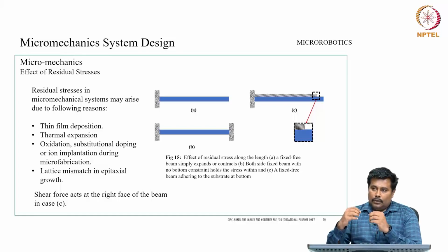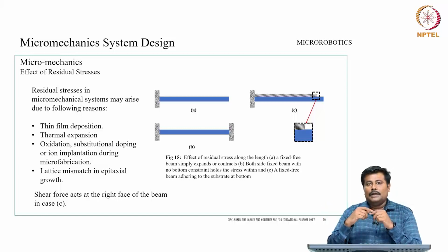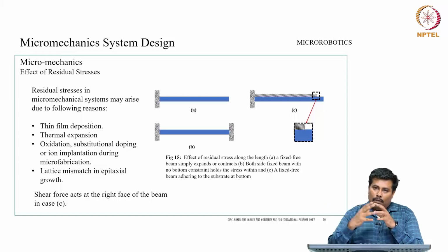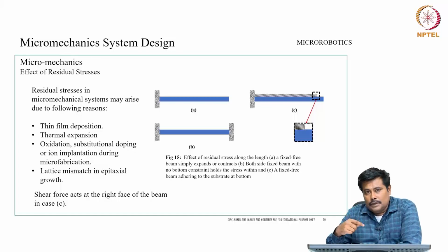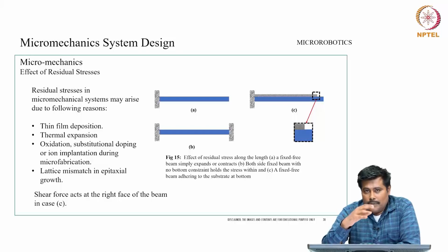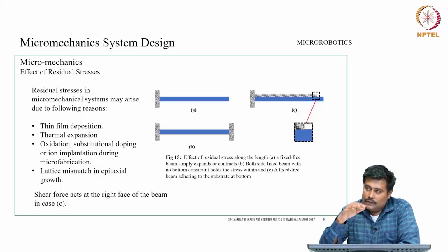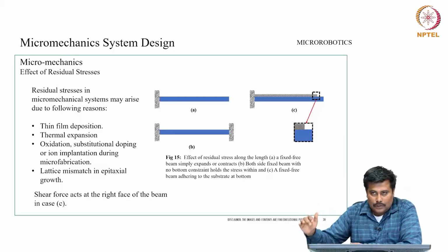When these springs are getting actuated, they will try to break the film. However, in due course of time, the oxide formation will start percolating into the lattice of these shape memory alloy structures, which will result in defect formation, and slowly the actuation behavior comes down.